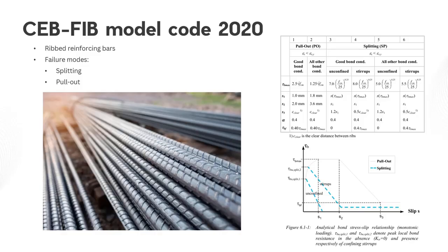Let me discuss first the pull-out failure. This happens when the surrounding concrete is well confined, with sufficient cover and transverse reinforcement rebars.